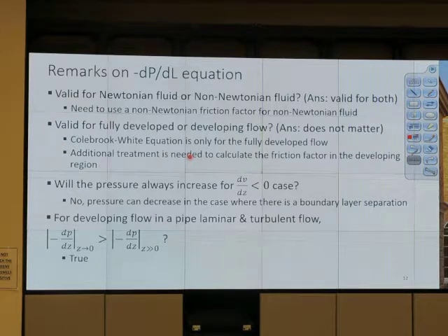Okay? What about flow of suspension? Certainly, we have fluid flow with solid particles inside. Is that shear thinning? You talk about gel, right? So a gel can be like a 3D network structure of solid phase. If you flow fast, maybe it breaks the particles into very small parts. It will change viscosity. To know it for sure, we have to do the test. So for those kinds of things, if it's two phase, most of the time it's non-Newtonian.